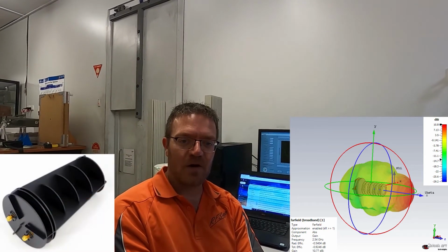Have a look. So I'm here today at Adelaide Uni doing some measurements. It's really a bit of fun and research work that I do, not as a sideline, it's really for customers and also for ourselves to educate ourselves with antenna performance compared to the CST simulations we actually do. At the moment I'm measuring Zebra, our directional 2.4 gig antenna that we developed. It's a 2-port antenna, so it can be used in a MIMO Wi-Fi configuration. It is circular polarized as well, so it has a lot of applications.